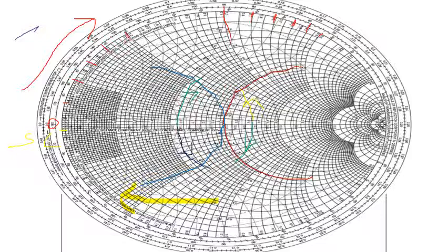But remember, when you take a solid arc, you move as shown in red in the clockwise direction from left to right. Now when you take dotted arcs, which is susceptance, you will always move from the opposite direction. Meaning we will be moving from here, because both cannot be the same. I hope you know both are inverse to each other.